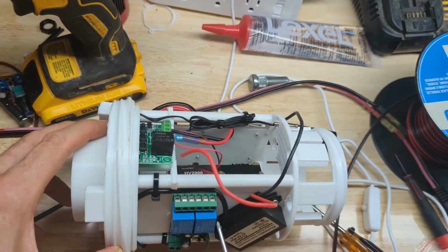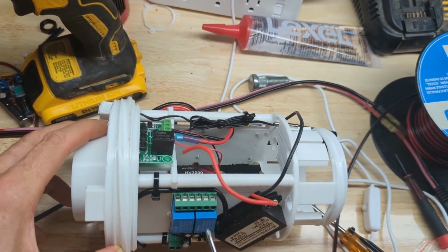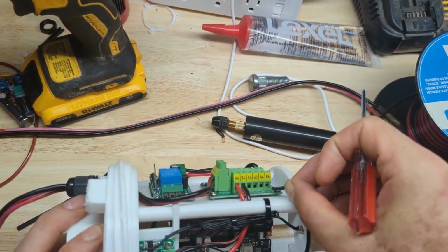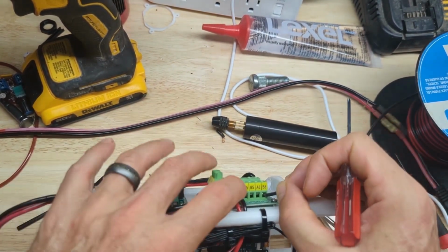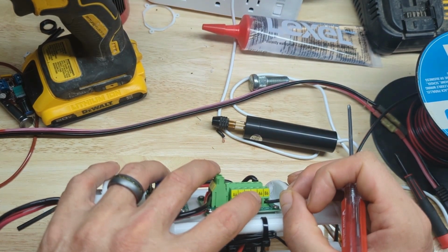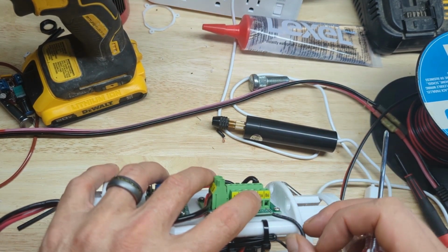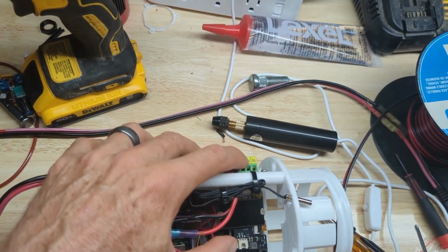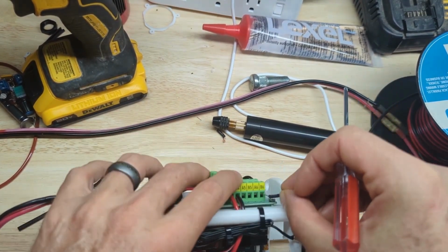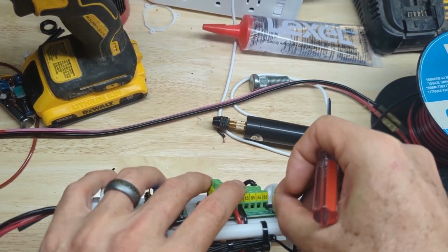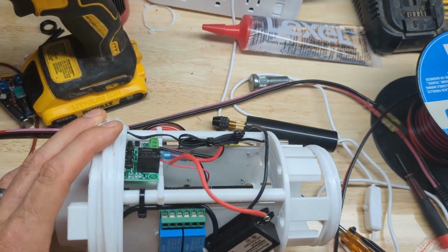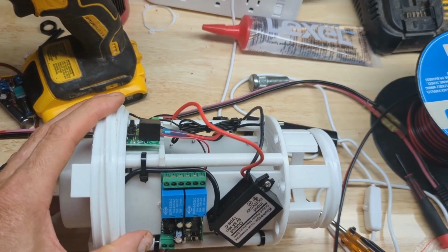Now, you'll notice we're not hooking up a negative anywhere on here, because the negative just goes straight back to the negative on the power block. So you'll recall our schema, we're using A as the positive and B as the negative. So we just take the ground wire for this power block, plug it into the B6, and that's all we have to do on that. So we'll go ahead and get this wired up, and we'll be back to it in just a second.